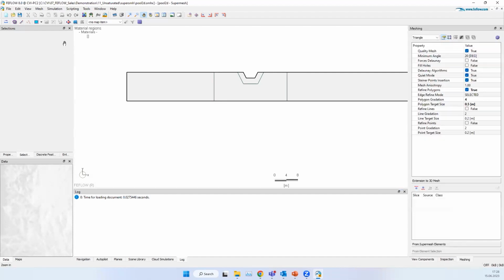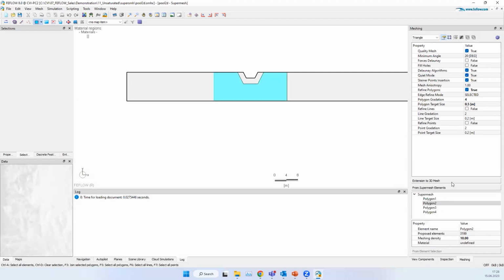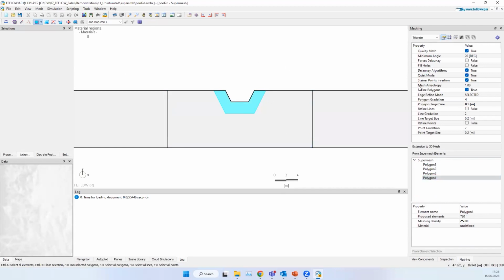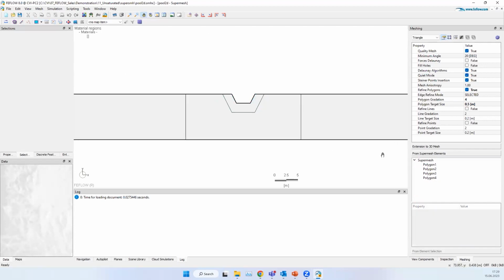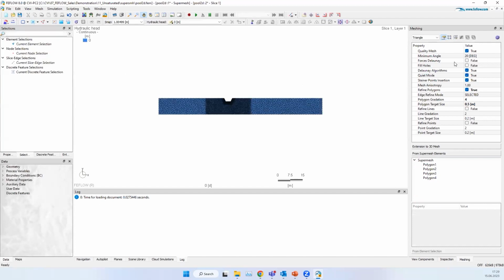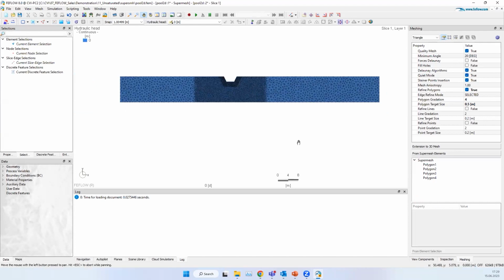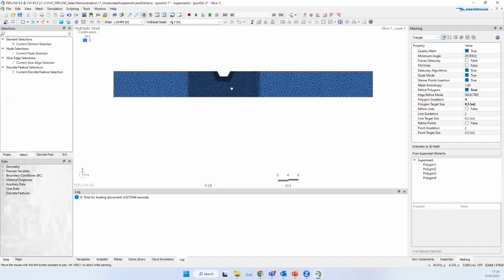And for this, going quick here, we use some specific mesh density factors, so 10 and 25. Then I have some gradations of the lines. I want to change the size of the elements gradually so we can generate a mesh out of that. So let's generate a mesh. Having this mesh, normally you would do some smooth operations. I will skip it because of the time, and let's put some boundary conditions.